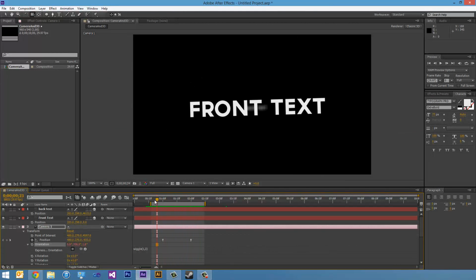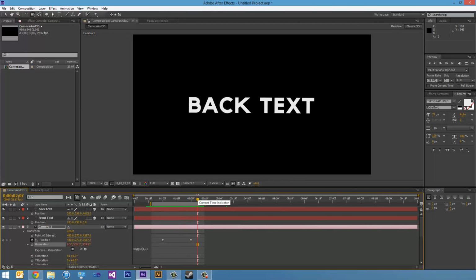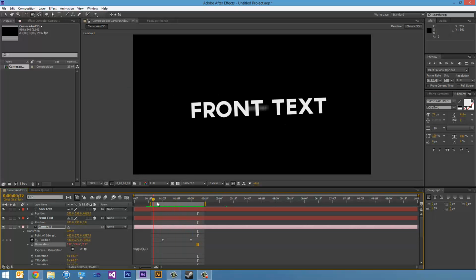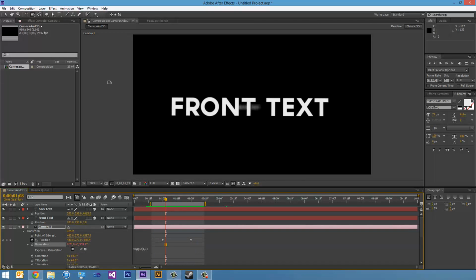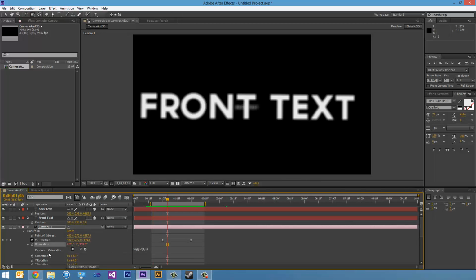So I wanted to do this in this tutorial because I wanted to keep the other tutorial dedicated to Element 3D. And then, we'll just throw in the camera, and what we learn from this tutorial we will use in the next tutorial. So this is a pretty basic tutorial, but I think you get the idea of 3D space and the depth of field and how to use keyframe expressions, keyframe equations, how to use the Easy Ease keyframe assistant.